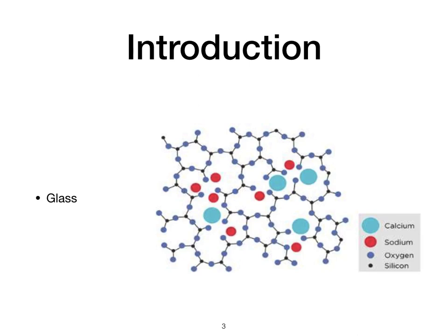Of the many silica based glasses that exist, ordinary glazing and container glass is formed from a specific type called soda lime glass, composed of approximately 75% silicon dioxide, sodium oxide, sodium carbonate, calcium oxide (also called lime), and several minor additives.